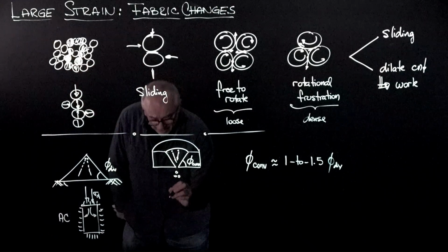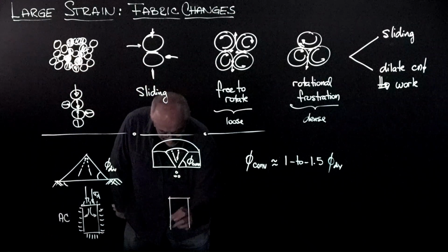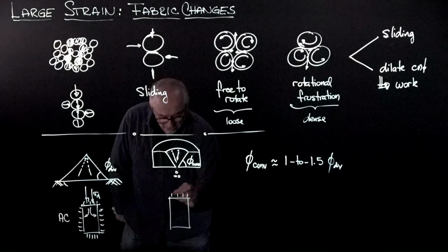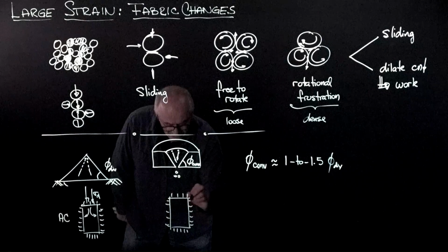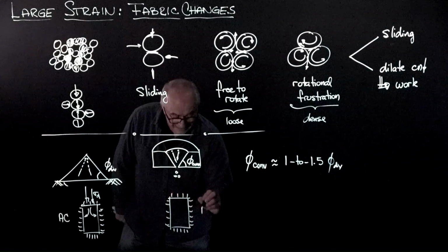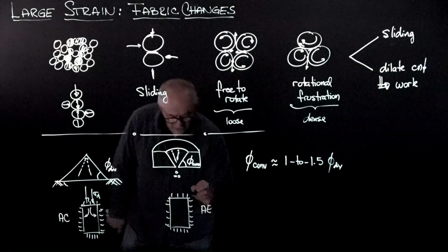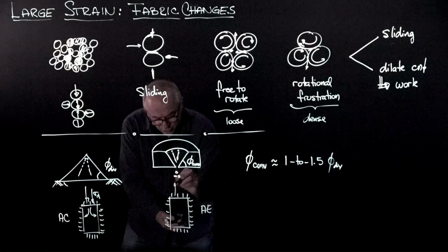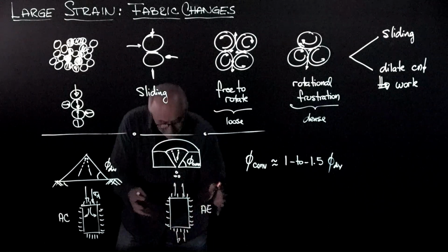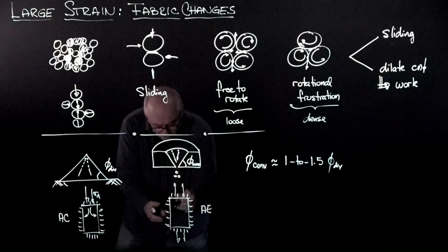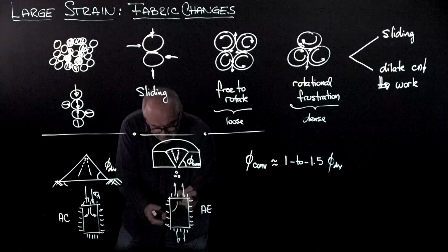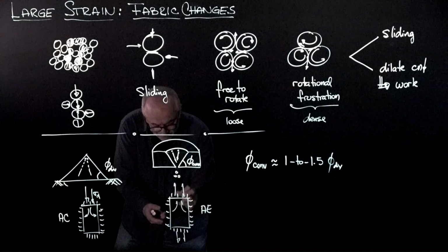However, if I do an extension test, and I can do an extension test in two ways. One is by axial extension, or the other one is by lateral compression. If I do an extension test and now I pull here, the specimen is going to get narrower and taller, and so flow is in such a way that it is convergent flow.